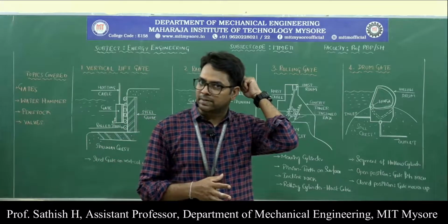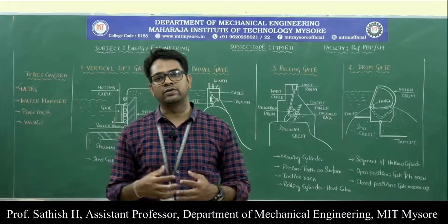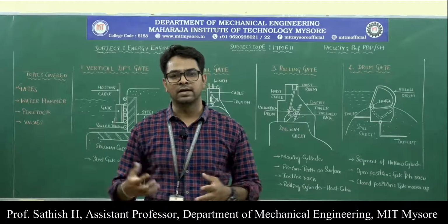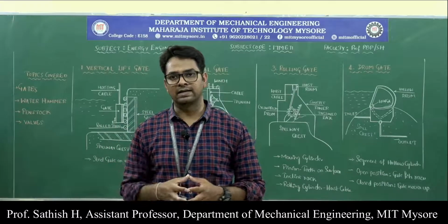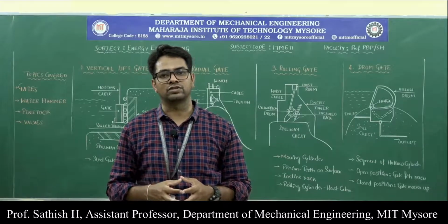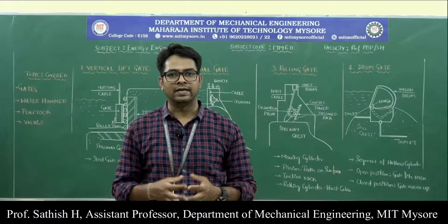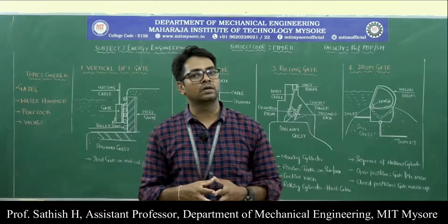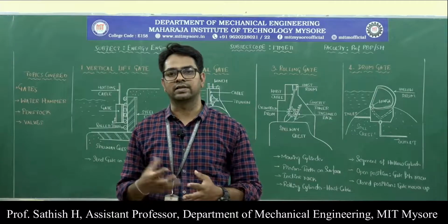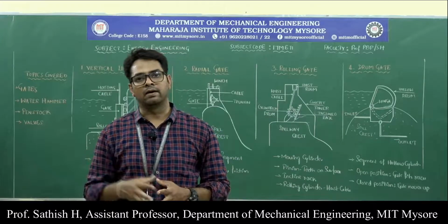In some cases, when the load on the generator is more, the turbine demands more quantity of water. So through the penstock a lot of water flows into the turbine inlet. That might create a high pressure, which means there are fluctuations of the pressure. In some cases the generator load is less and the water required by the turbine is less, and in those cases a vacuum might be created inside the penstock or the closed hydraulic circuit.